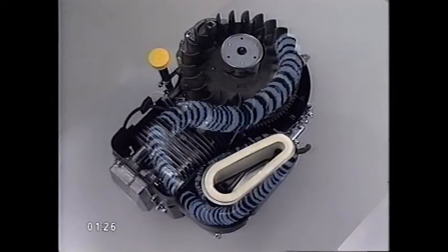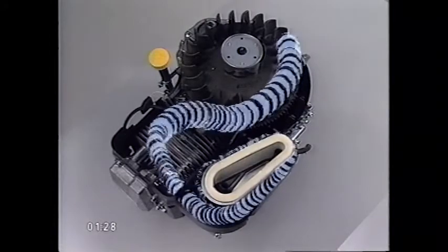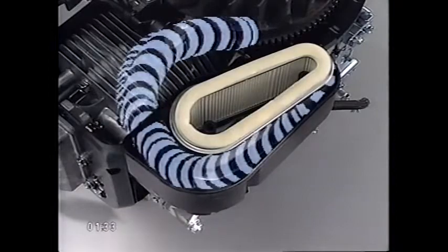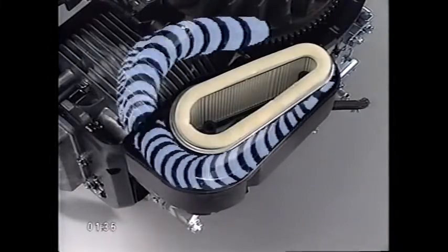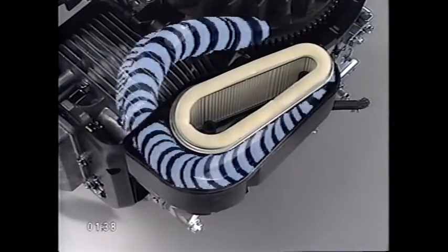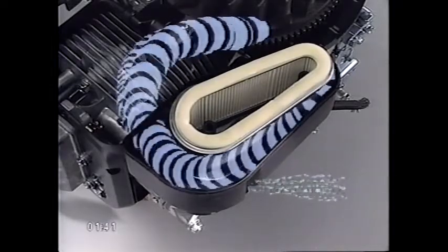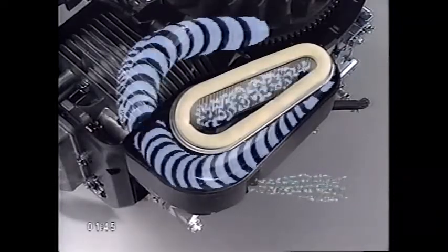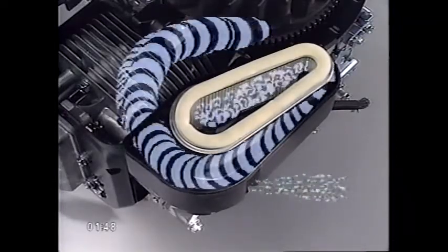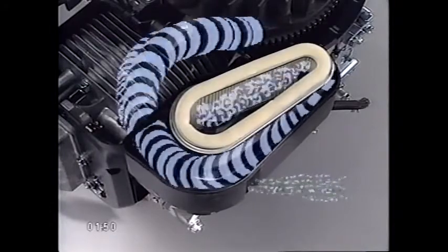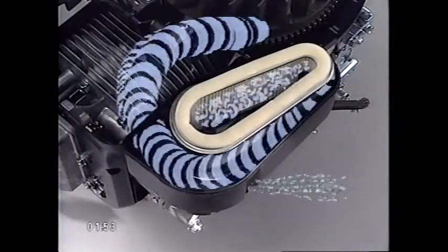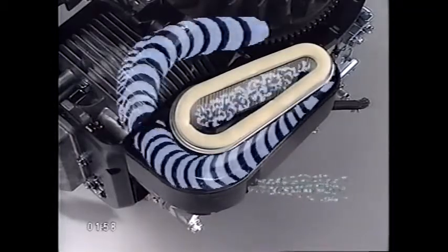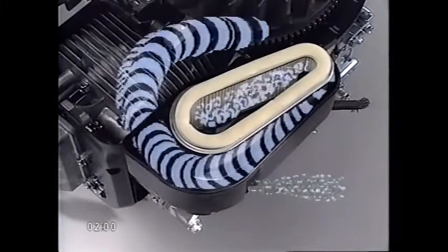After the air leaves the blower screen, it travels under the engine shroud and enters the filter housing. Since it's moving at a fairly high rate of speed around the curve of the housing, centrifugal force throws the larger particles of debris and dust out the side. The remaining air, which is relatively clean, enters the air filter. Keep in mind that the volume and velocity of the air is controlled by the design of the housing. So if anything changes the path of the air, it will affect the operation of the carburetor. This includes dirt clogging the air filter.